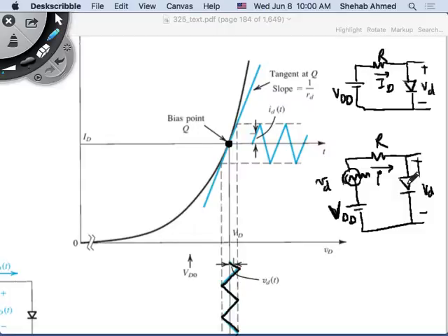How can you know that? It's if this voltage V small d is small with respect to Vt. So if V small d over Vt is less than 1. Vt we said is what? 25 millivolts at room temperature.